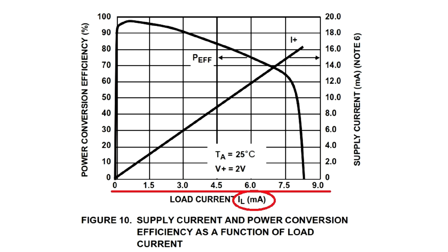As of today, the same thing is true for any converter that relies on switched capacitors alone. Therefore, the charge pump is a rather exotic topology, which doesn't play an important role in power supply design. Thus, I will not make another video about it. I simply wanted to show you that such a switched capacitor design is possible.